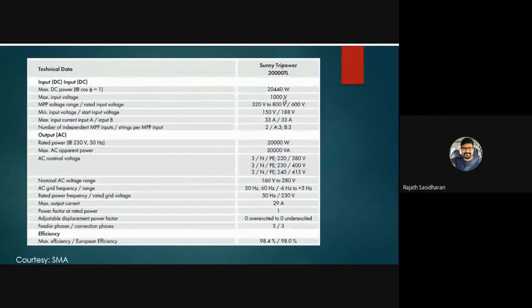In that case, the open circuit voltage of the panel will go above what is shown in the data sheet. So that's a bad practice. Ideally, we have other simulation tools to really make sure that the open circuit voltage of the panel will not exceed 1000 volts. But just for thumb rule calculations, for predictions, you can do that, but not for actually designing a solar photovoltaic system.